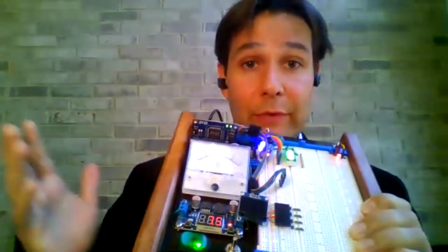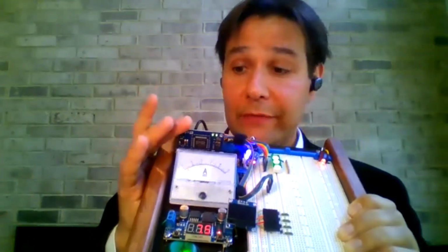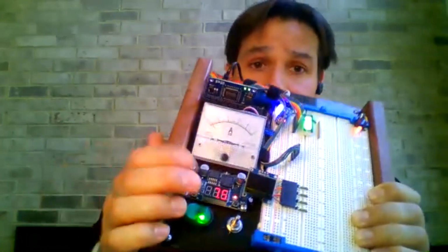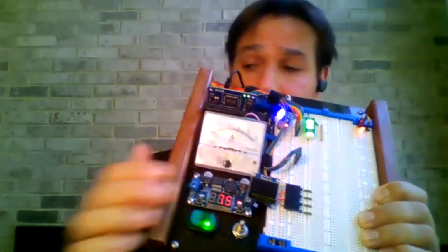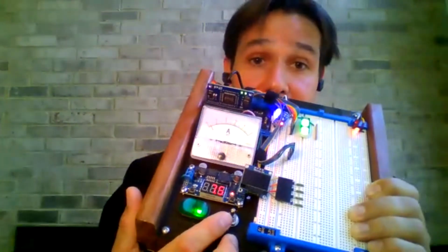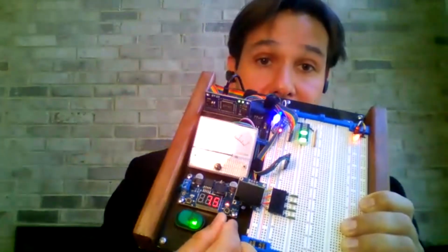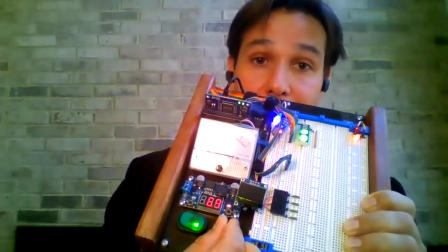So it might be interesting to see if we can have some kind of a switching power supply based off one of the smart pin modes that runs off the P2 chip. I got this little boost converter you can get off of Amazon. It's nice because it has the display as you adjust it. Actually, I took off the trim pot, desoldered that, and hooked it into this larger pot so that students could use this to adjust their variable power supply.